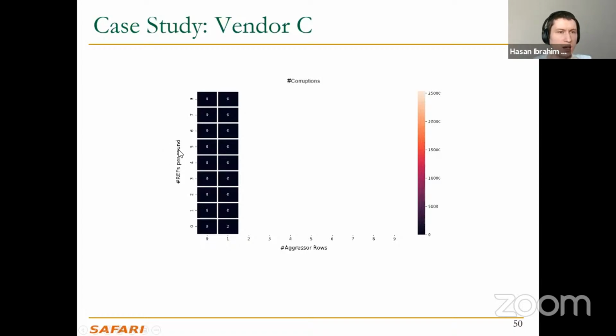And a round is basically how many times we repeat an aggressor hammer and refresh cycle, right? So we call this a round. Initially, if you have 0 aggressor rows or 1 aggressor row, we do not observe any bit flips when we perform at least one refresh operation. And when we don't perform any refresh operations, we are able to observe 2 bit flips. This is across 512 rows within one bank, so this is not across the entire bank. Only 2 bit flips, right?